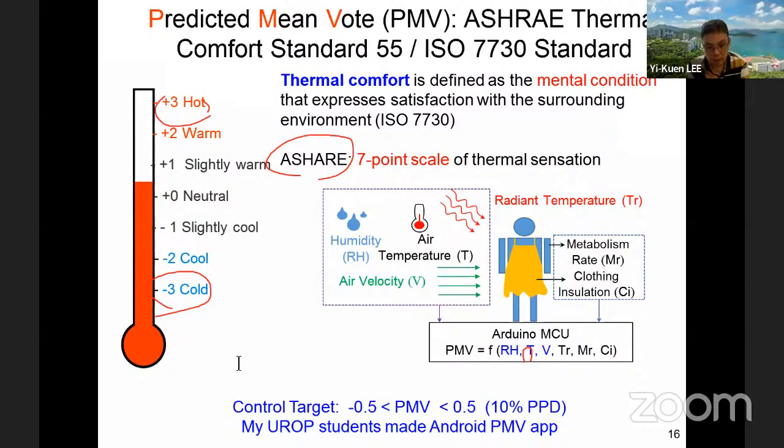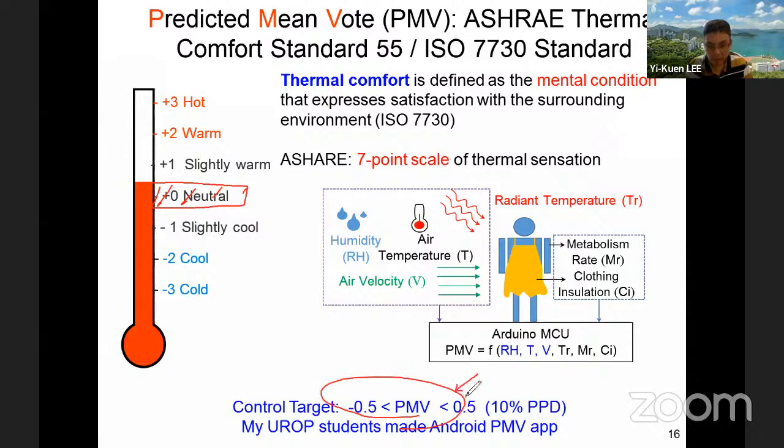Okay, so TR is related to radiant temperature. These are the ones which can have a big impact on our human thermal comfort. And then of course, as I mentioned, for our PMV we hope we can achieve ±0.5, like here. This range will be good as a method for control. Right, in this case, with PPD, I hope you still remember what PPD is.